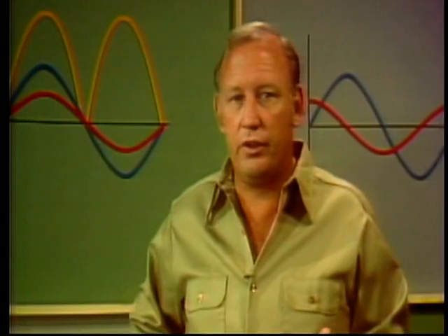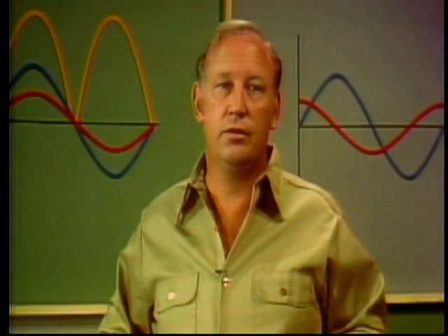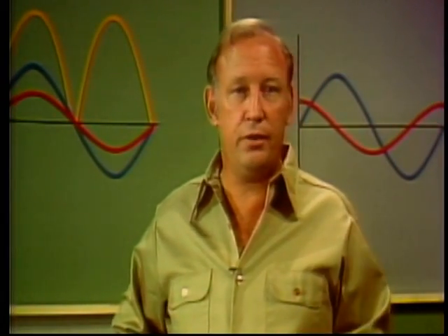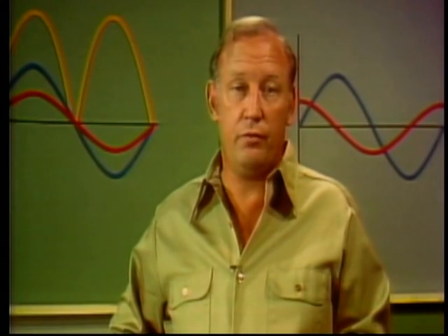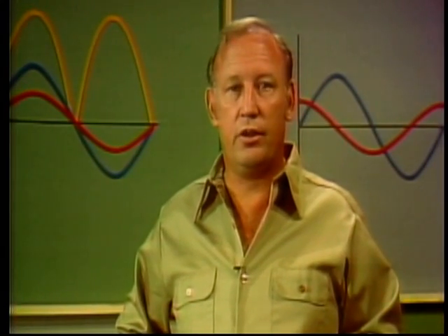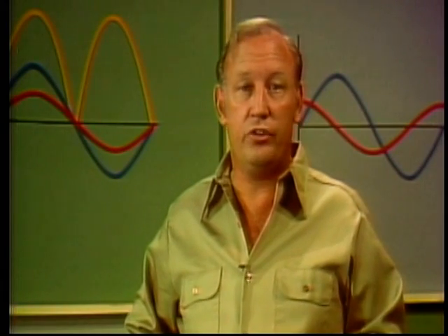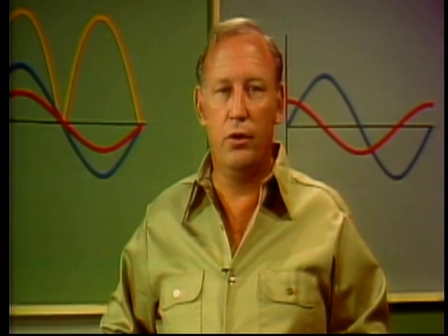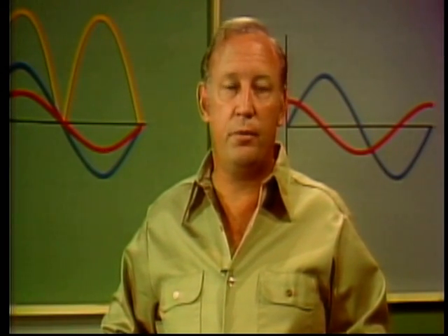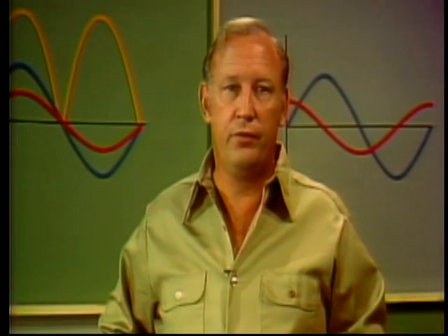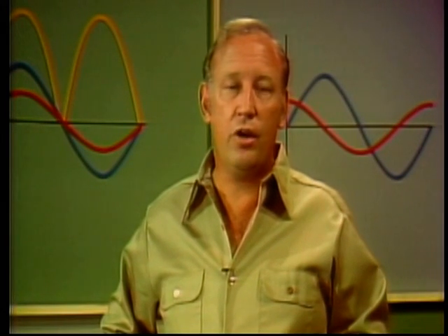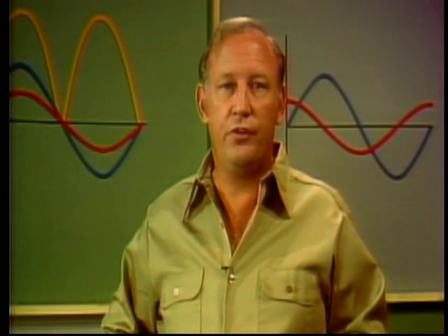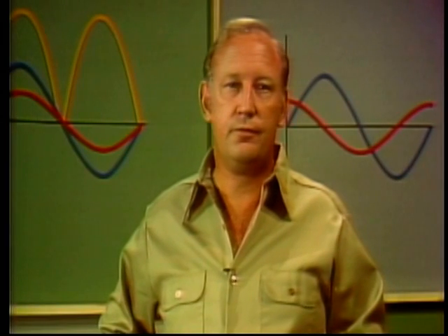What we just saw was a conductor in a changing magnetic field. With a conductor, a magnetic field, and relative motion, we get voltage. In this case, a current-carrying conductor induced a voltage in itself, so we call the process self-induction. As the magnetic field moved outward, the voltage induced in the conductor was opposite in polarity to the applied voltage. This opposite voltage is the CEMF. Because it opposes the applied voltage, the CEMF limits current.